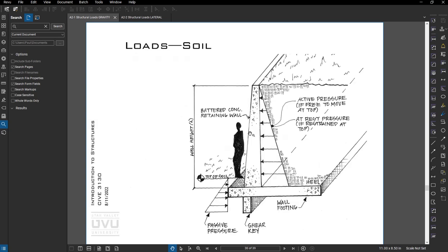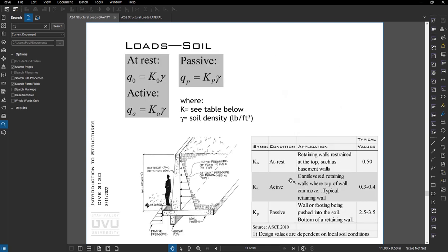Okay, so retaining walls, basically they're creating steps in the earth. We use these on slope sites all the time. We basically have the pressure of the soil pushing one way and the passive resistance of the soil pushing the other way, because this creates a moment. As you can see, if you sum moments about the centroid of the triangle here, this has an eccentricity. The weight of the soil here pushes back down and keeps it stable.